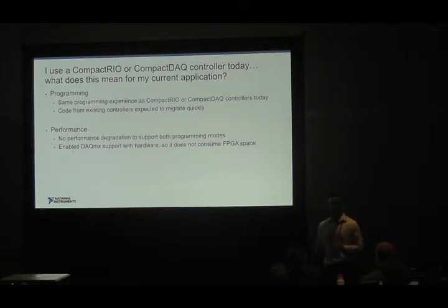Depending on which mode you choose, you will have different paths and different routes for DAQmx data versus LabVIEW FPGA data or RSI data that may be coming across. One of the common questions is, if I have a control application today that uses the FPGA and I want to add in DAQmx, how much FPGA space am I consuming? And the answer is 0, because it is truly a completely different path.